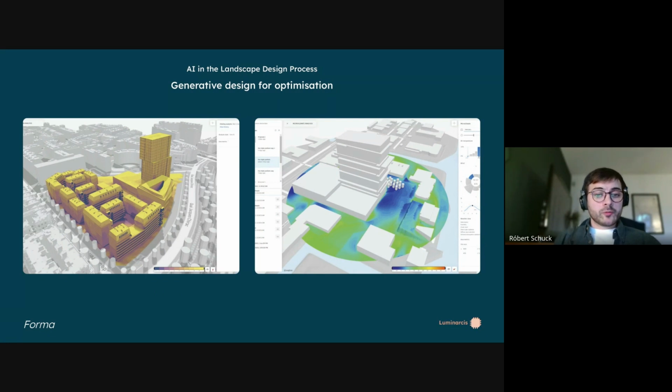So as you update the model, it's going to update also the analysis to see how the buildings affect sunlight exposure, wind sheltering, noise sheltering, and if you work together, you can ensure that the outdoor environments have the maximum thermal comfort and the best noise filtering. So you can really ensure to create pleasant outdoor environments.